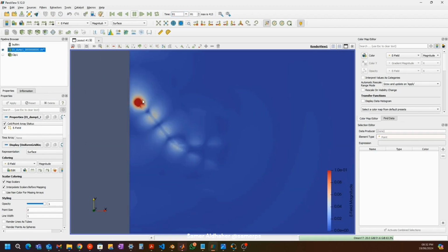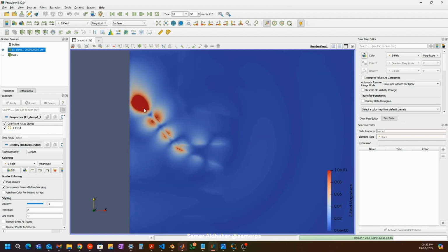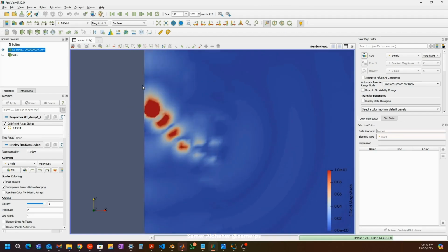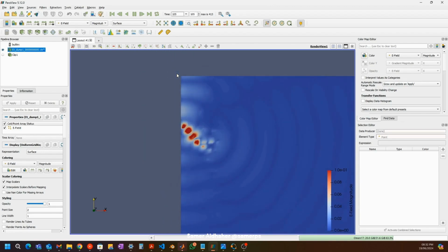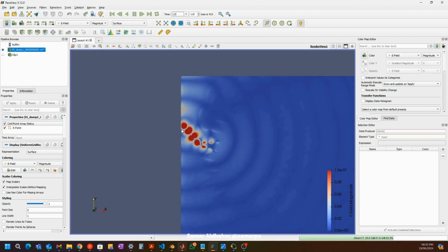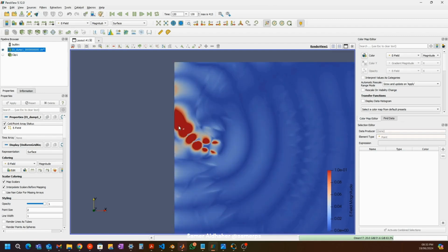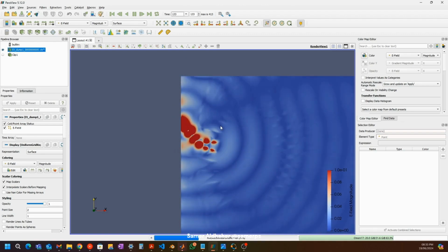See, this is where the signal is being fired. It does fire from all angles, so you can see here it goes from where the trace is, but also goes behind the trace, and you can see signals start to appear slowly, and there it is. The signals going behind the port are reflecting and bouncing off the PCB edge. Of course, you can fix this depending on the port that you define, but I think it's fine for what we do.